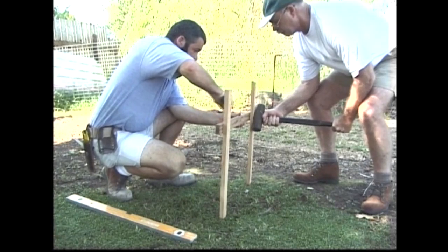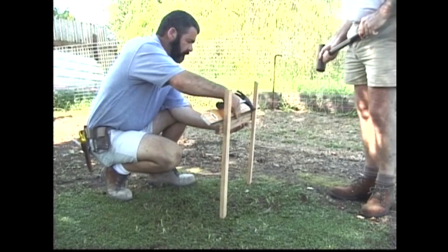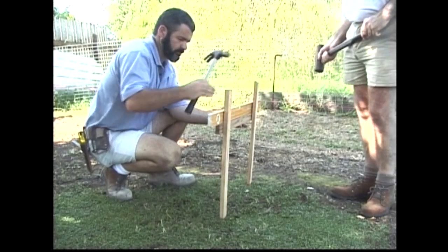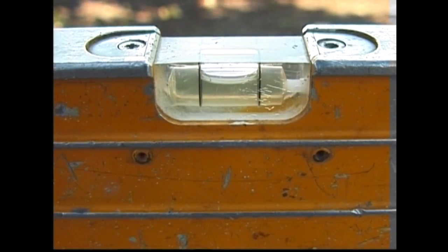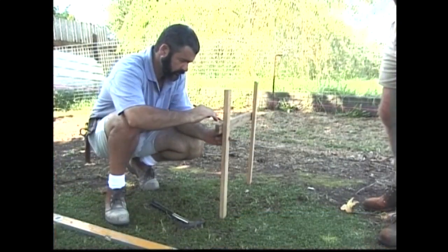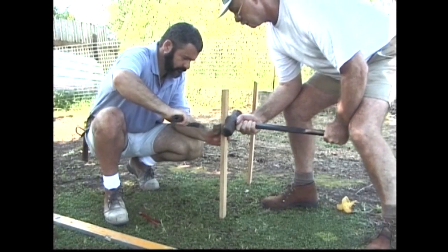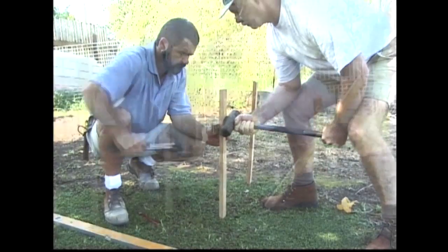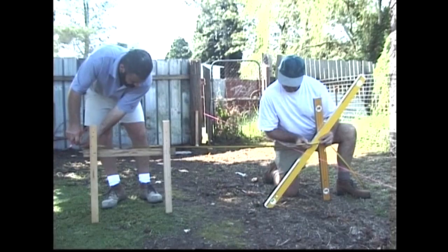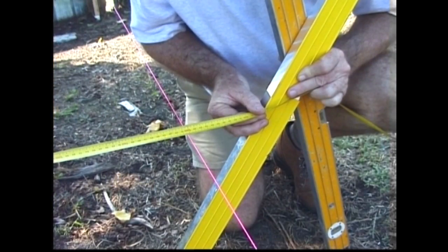The tops of the ledges are fixed at these marks and levelled across the profiles. The side setback distance indicated on the site plan is measured square off the side boundary string line to each of the 2 profiles.